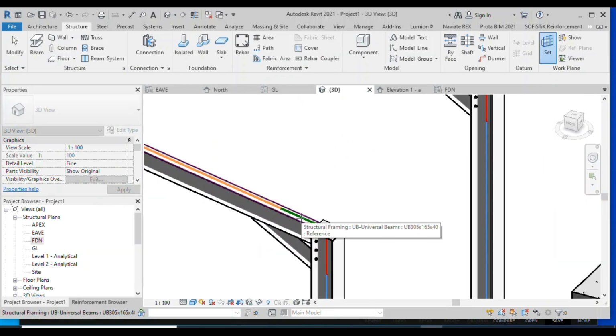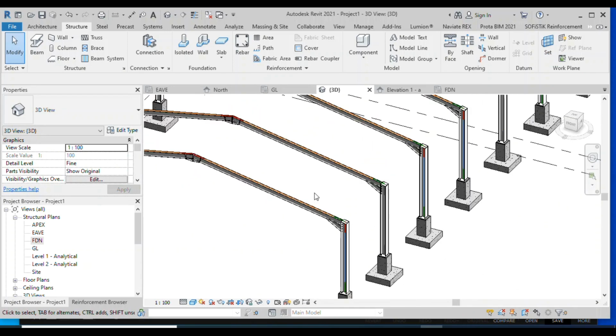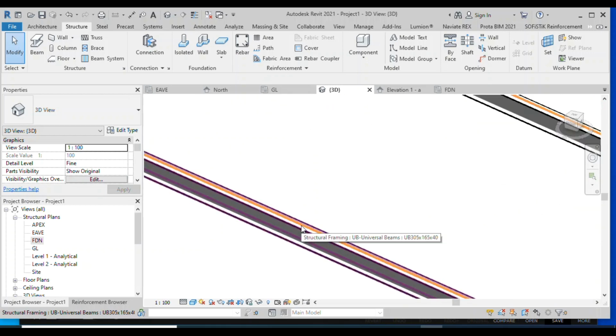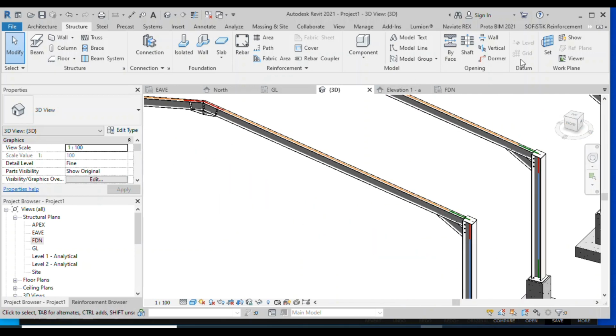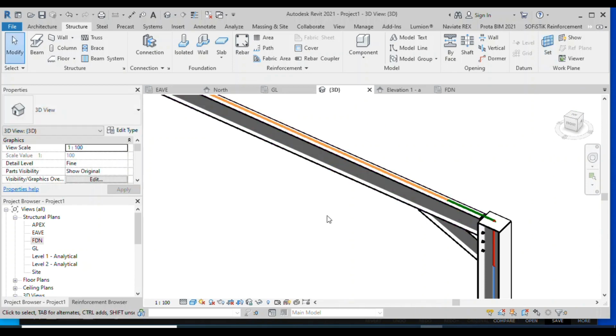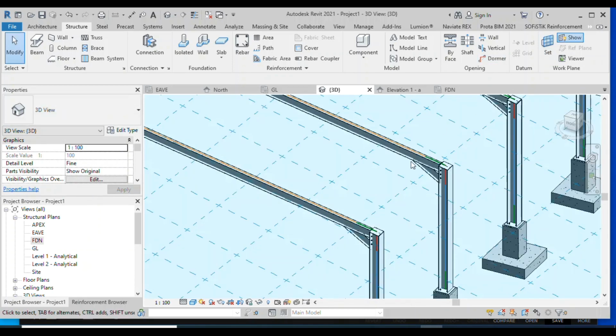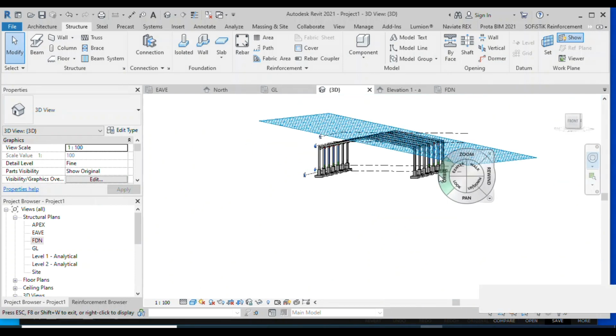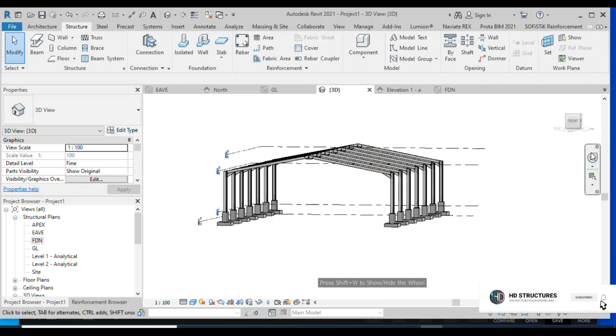Now pick the top. Yeah, the top has been picked. It's not that you just pick the top. Let me go over it again. You come to structure, you select, you pick plane, then you make sure that you hover on the top of your rafter, then you left click. That's been selected. To confirm, you click on show. If you click on show now, good, you see that we're working on that plane.